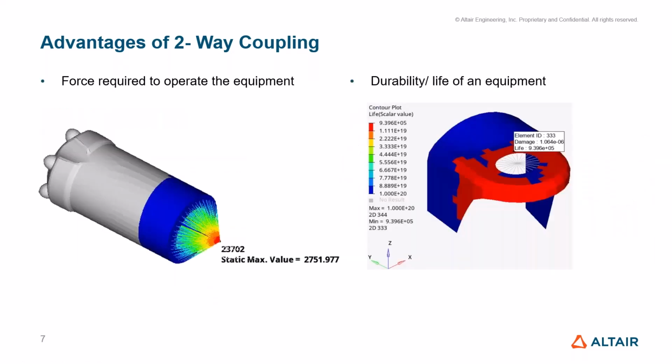The next one is in terms of the power calculation, or the force as an output required for any enforced motion conditions. It's easy to obtain from the FEA solver as a reaction force. If you apply an enforced displacement as an input, in return we can expect a reaction force, which is the force required to move a complete system, and it can be obtained very easily.